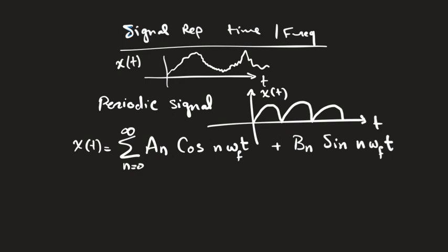So we know that a sine wave that looks like this, assume this is a sine wave, okay? When I look at it in the frequency domain, I will find that versus frequency, it exists only at a single point with some value, right? We call that the delta function because it exists only at a single point, right? And that point is a particular frequency, that omega_f, if it's versus omega, okay? So any sinusoid has a particular frequency. That frequency is the single frequency contained in it. It doesn't have any other frequency components, okay? And the amplitude here is dependent on the amplitude of the sinusoid. These are those amplitudes that we have here.